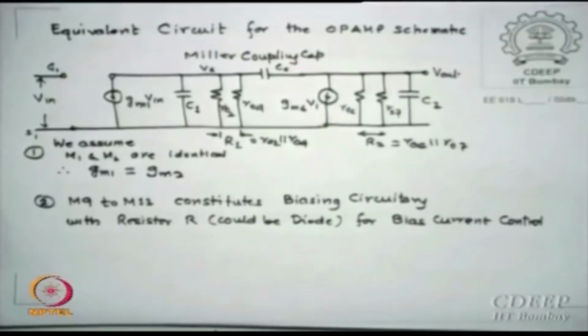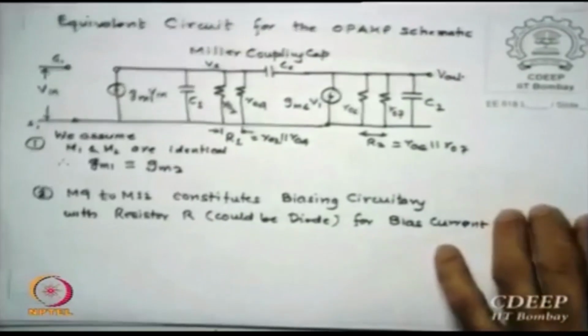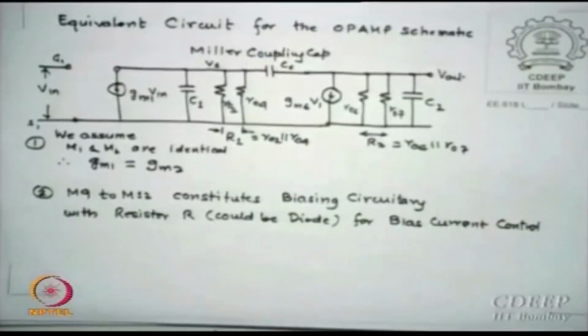Maybe we need it where there are issues, something about which op-amp you have done in second year or third year. I do not know, where do you see analog lab, second year isn't it. There is one experiment we ask you to find out offset voltages. Between the two inputs, if I do not apply anything, the output should be 0, but it is not. So you apply a difference, some opposite, so that V0 goes down. One technique of offset cancellation is using a differential system. That is why I say it is used many times for offset cancellation inside the chip, not externally. Inside we will do something so that offsets are 0.